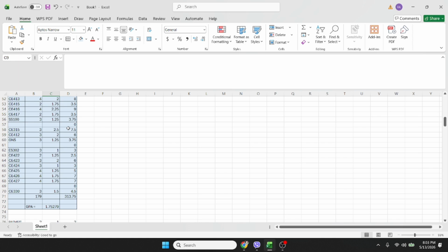So for beams built integrally with supports, VU at the support shall be permitted to be calculated at the face of support. Sections between the face of support and a critical section located d from the face of support for non-prestressed beams and h/2 from the face of support for prestressed beams shall be permitted to be designed for VU at a critical section if A through C are satisfied.